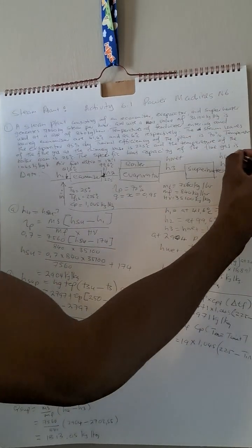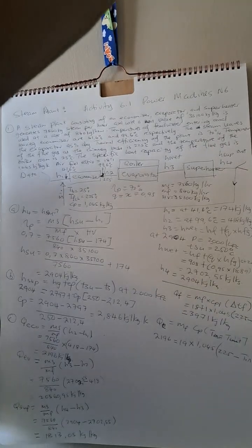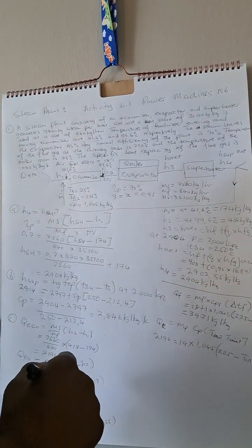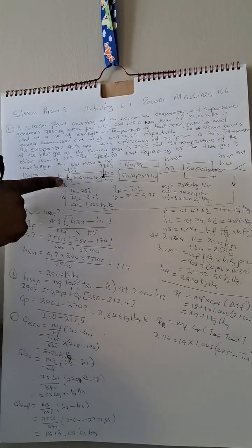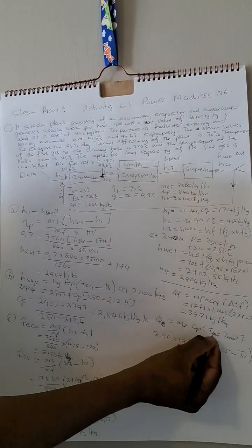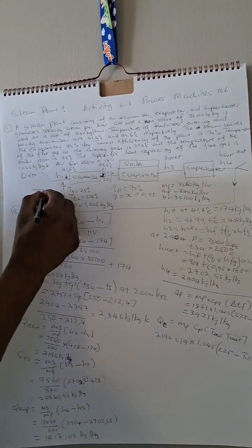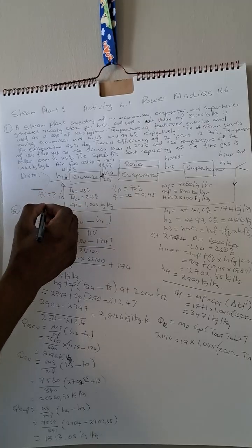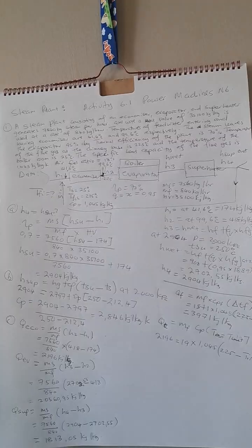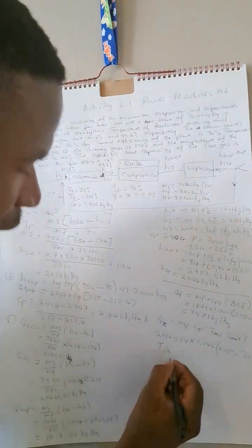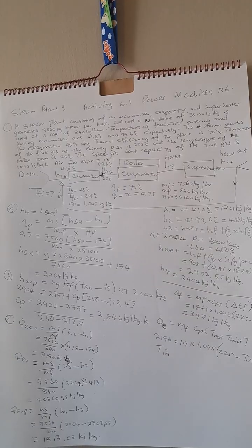So when they are sent back here, they are now entering, this becomes T in. But remember, we had already out here. Remember, these are out because the superheater is going to the industries, wherever it is going to be used. But we still have the returning flue gases, which come at our T in. So this becomes our T in. This is the one that we are looking for, this temperature. This is the temperature which is in question, because T out at the chimney base is said to be 225. So from there, we can get our T in. Let's look for our T in.